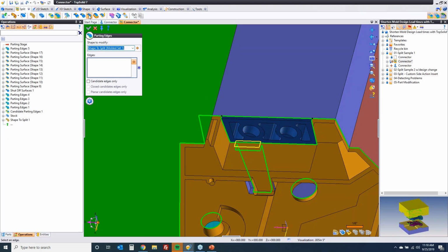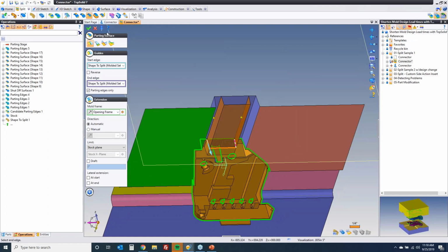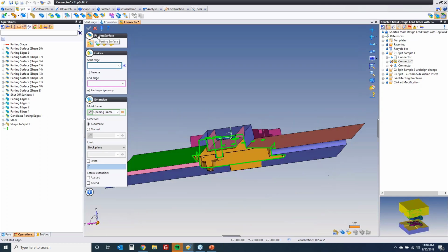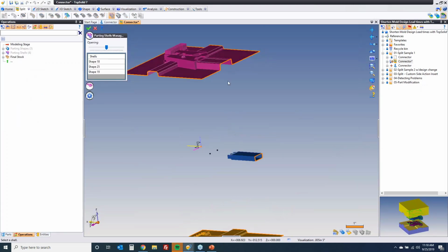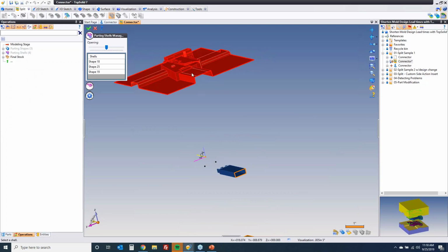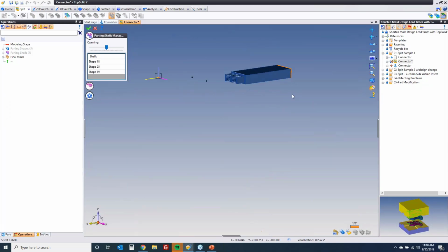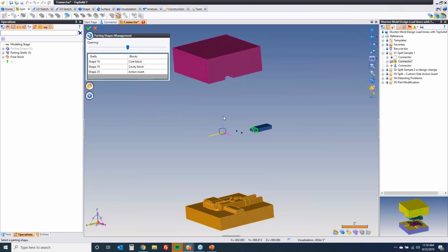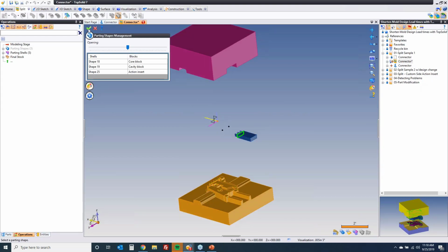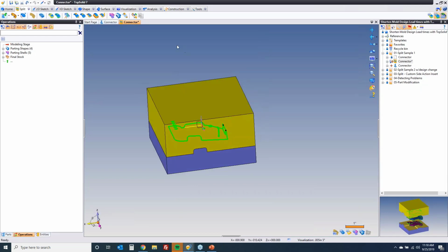Now what are we going to do with this? I'm going to just go add the missing surfaces. All I'm going to do is take from that edge to that edge, let it extrude out, and we have all the information we need now. Watch, if I update my parting shells, notice now the cavity still looks like the cavity. The core, however, has changed, and we now have a set of insert surfaces. If I update, it's going to create the new blocks, and like that, we've added the roughed in insert for the side action. Kind of cool.